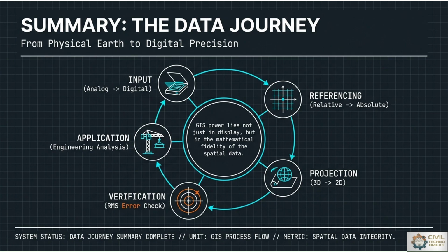Next, map projection. The earth is an irregularly shaped ellipsoid, but our maps and CAD drawings assume it as a flat surface, just like a 2D plane. So map projection is the mathematical formula used to transform the 3D surface of the earth into a 2D plane. No projection is perfect. They all cause some degree of distortion in area, shape, distance or direction.